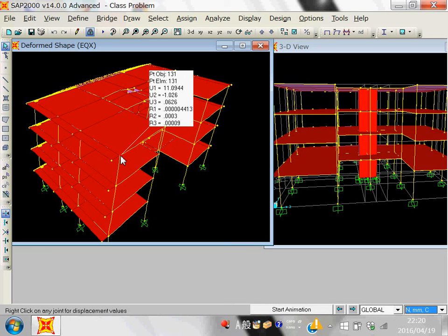For some cases, it is H over 100. For some cases, for example, for the vertical horizontal deflection, it is H over 360. The length of being over 360. The horizontal deflection should not be more than that. But for the first portion, H over 200 will be very small. It will be 20 millimeters. Okay. Now I tell you how to see